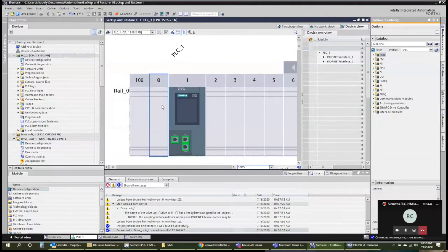Well, yes and no. The PLCs also support a number of other protocols, like Modbus TCP, for example. So if that drive talks Modbus TCP, then you can communicate using Modbus TCP on that same exact network that we're talking on Profinet. But ideally, you'll save yourself a boatload of time by just getting the Profinet version of that drive.